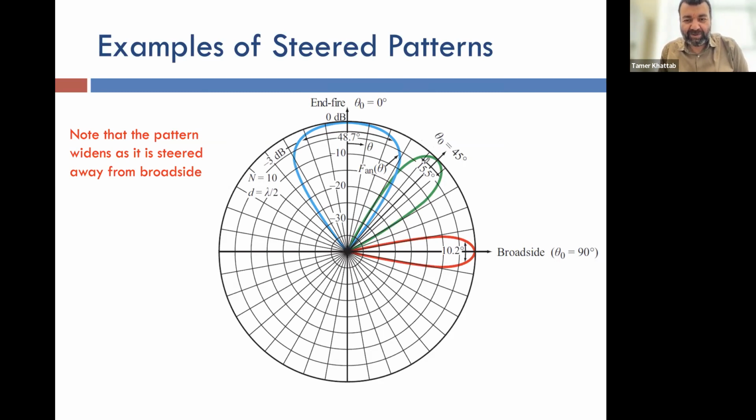The advantage is you can do it easily and quickly, because this is done using digital signal processing techniques that can do the steering very quickly and very cheaply compared to a mechanical element. It does not require that much maintenance as compared to the mechanical. However, the disadvantage is you have some losses in terms of getting a slightly wider beam. So your beam becomes wider when you are steering away from the broadside. Any questions about electronic beam steering?